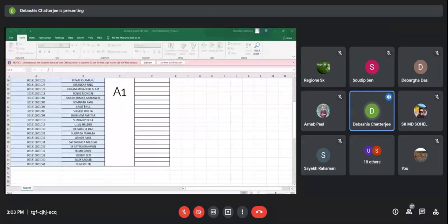That means looking at the dimensions of the machine, you can guess what could be the power rating of the machine. You cannot extract large power from a very small dimension machine. That is your own idea also. When you go to see different motors in your laboratories and in your domestic applications, fans and all, they are very small. So their power is small and their volume is also small. So first is to get the main dimensions.